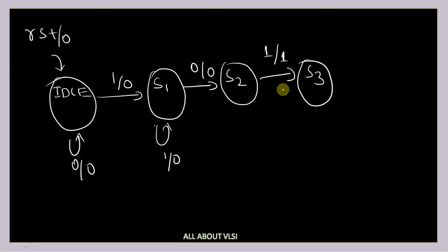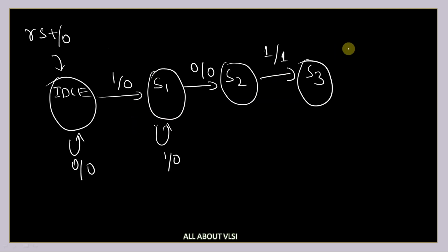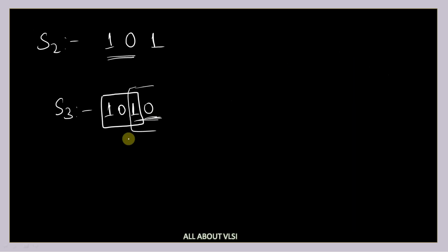Okay. So I'm talking about overlapping, right? So I can overlap this 1, 0. Okay. So 2 bits are matching. That's why I'm going to a new state which is known as S4 state if my input is equal to 0, by making my output equal to 0. Previously, if I got 0, I stayed in the same state. But here if I get 0, I go to the next state, S4, because it is overlapping and two bits are matching. Okay, is it clear?